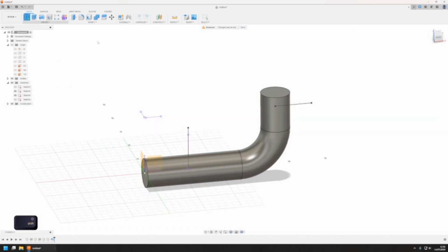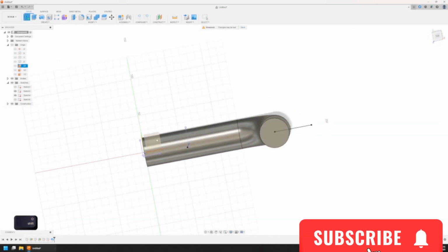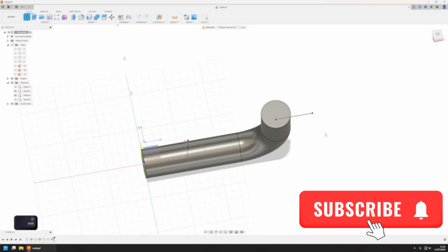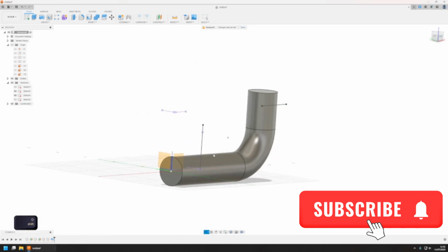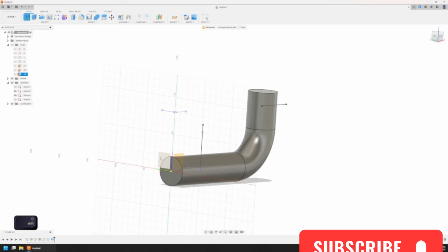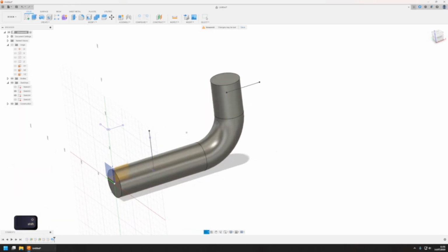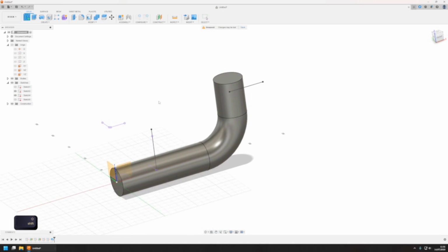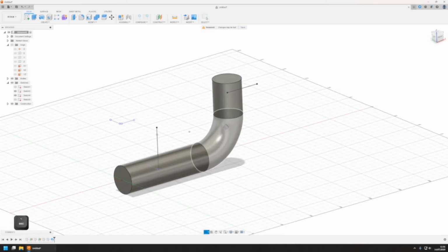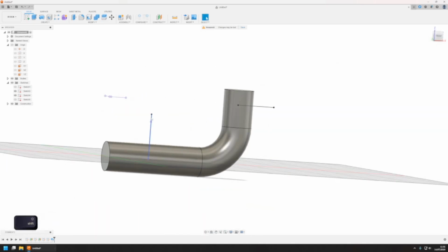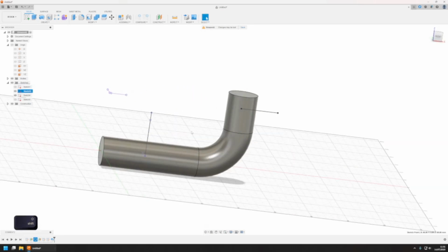Again, you might be tempted to just go create sketch on this plane and this will work perfectly fine. You might be able to create a sketch on this one and select like an offset and start from here to here, and that'll be perfectly fine, but that's not really the correct way to do it. The correct way to do it is to create a point perpendicular to this line in this point, or in this one, it doesn't really matter. I'm gonna do it in this one because it's not inside the part.